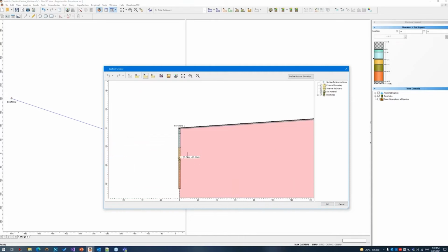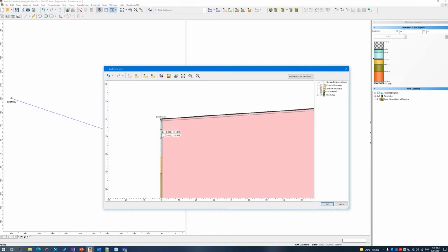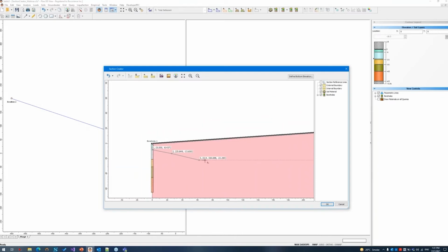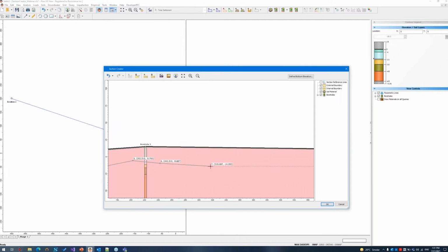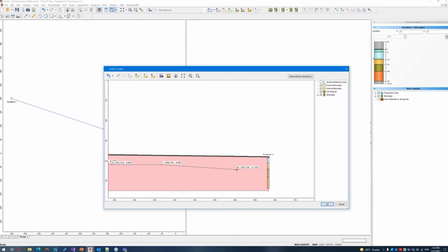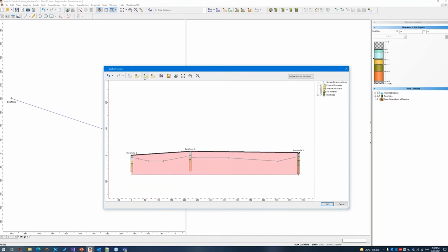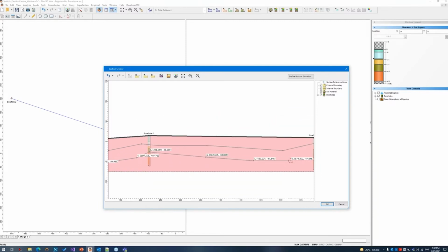But we are not restricting users to draw the internal points always following the borehole layers. For example, you can click the starting point at any point over here or at some other points in the middle like this. And you can even skip the middle borehole like this to make a boundary without using these boreholes. So that's what I mean in the slide. The boreholes will be a guide rather than any restrictions. So let's define another layer over here, for example.